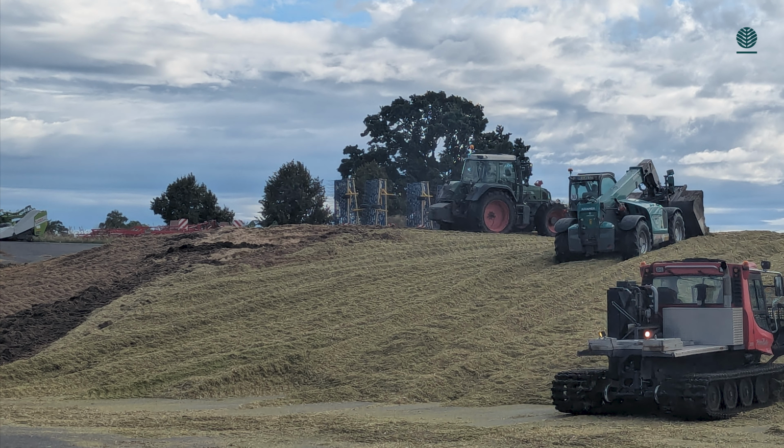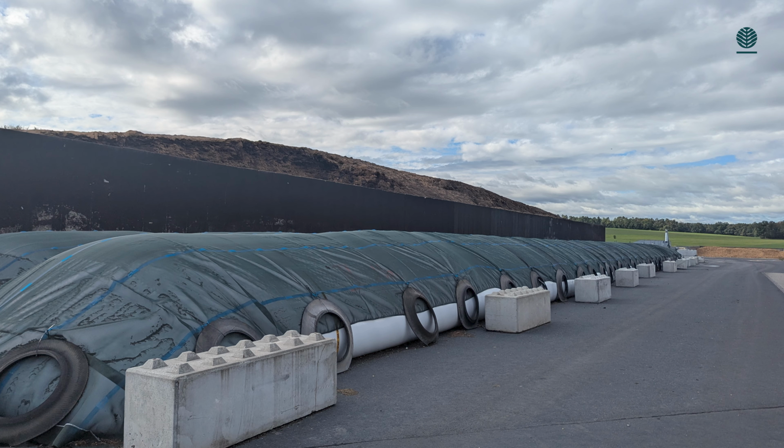In the pictures you can see where the feedstock is brought in, a drive-in silo. What you can see here is maize silage. My guess is it's quite close to Napier grass. We seal it to avoid oxygen, because we need to store it for a whole year, since in Germany we have only one season. It's starting now, where maize can be harvested, and then we need to store it for almost 1 year.